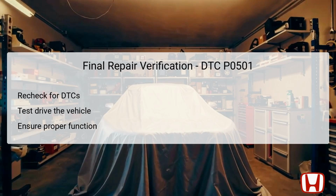After completing the necessary repairs, it is vital to perform a final verification process to ensure that the issue with DTC P0501 has been resolved. Start by reconnecting the HDS to check for any new DTCs, ensuring no outstanding errors remain after repairs. Next, conduct a test drive of the vehicle under various driving conditions to observe if the transmission operates smoothly without any warning lights or erratic behavior.